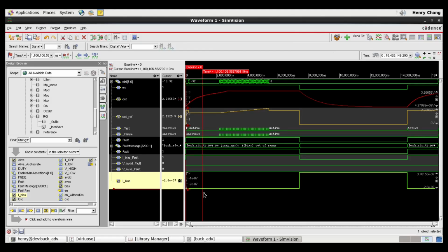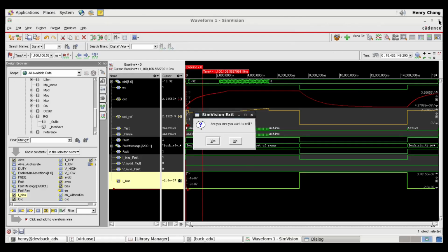It can often take days to get a chip level simulation going. And one of the reasons it can often take days is that the setup isn't quite right. There's an incorrect bias somewhere, there's an incorrect voltage reference somewhere. There could be hundreds of bias lines and tens to hundreds of voltage reference lines. By being able to quickly isolate where the faults are, we can quickly debug our system to make sure the setup is correct as far as bias lines and supply lines go.